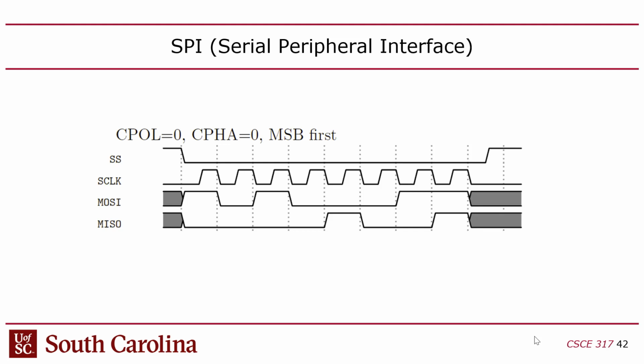Potentially like 3 feet long, right, is the idea. And those wires have capacitance. The longer the wire is, the more capacitance. So when I say stabilize, what I really mean is charge or discharge the capacitance of the wire, right? And also, the more time you give it to stabilize and charge up, the less likely it is that when you actually clock the data in there'll be an error, right?